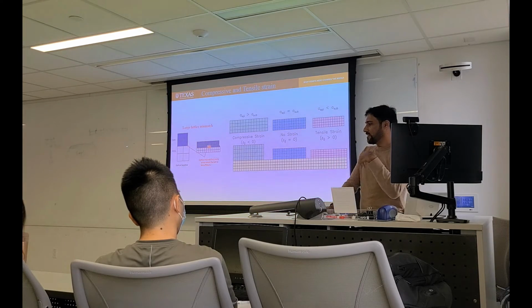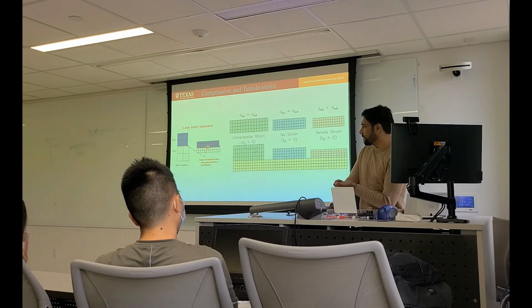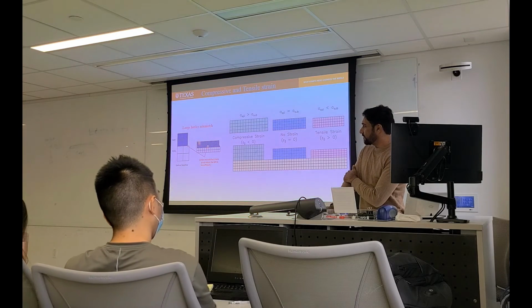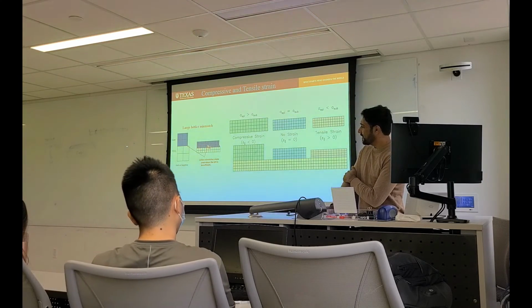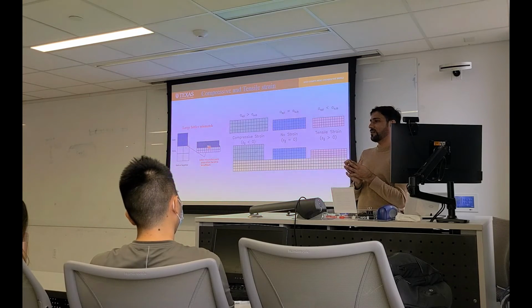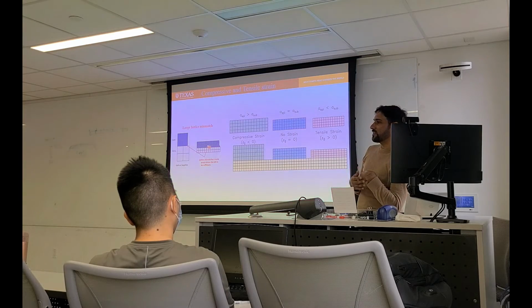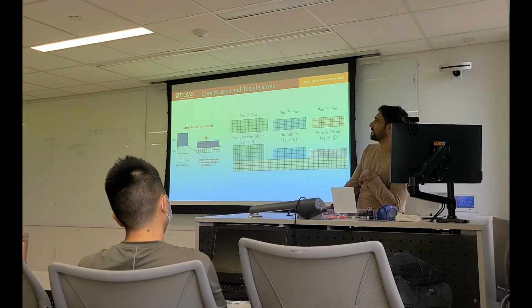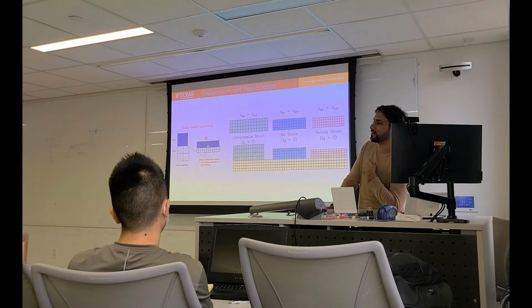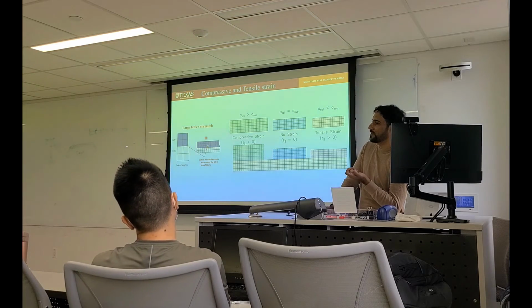Then they reduce the pressure and increase the temperature. Then they go to high temperature. In that case, this buffer layer compensates the strain. Not fully, but crystal quality was much improved. So when we increased the thickness up to 3 micron, 4 micron, the crystal quality was very nice, even LED work.